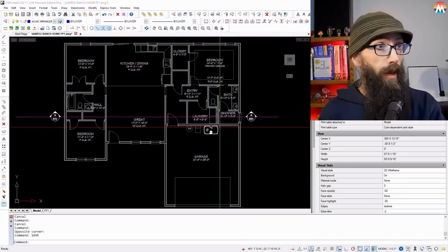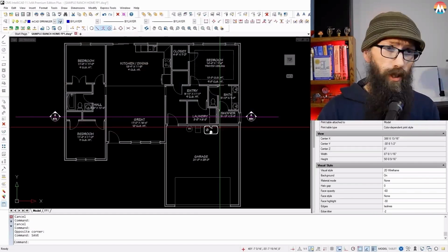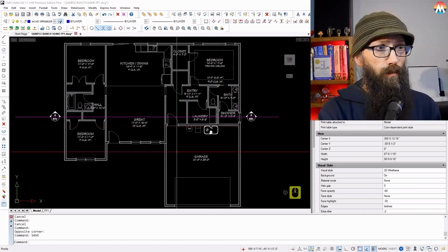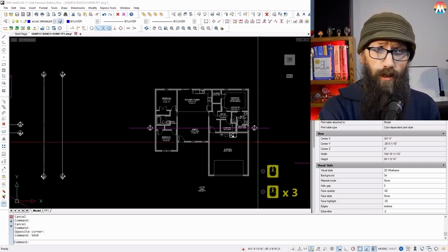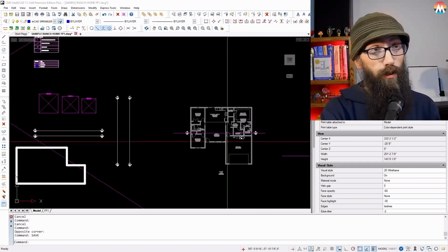All right, guys, we are getting started on our pre-calc checklist, and we are going to start with labeling areas that are not requiring sprinklers. So let's go ahead and switch over to our CMS IntelliCAD. The 2 main areas that we are concerned about with this project specifically are bathrooms 55 square feet and under, and closets 24 square feet and under. And that's the two main things that come up in this project. It's also, quite frankly, the ones that come up over and over in general, like 90% of the time.